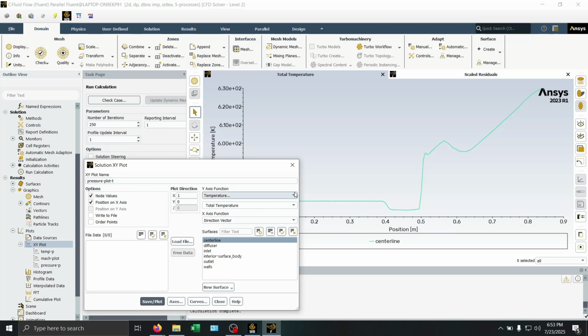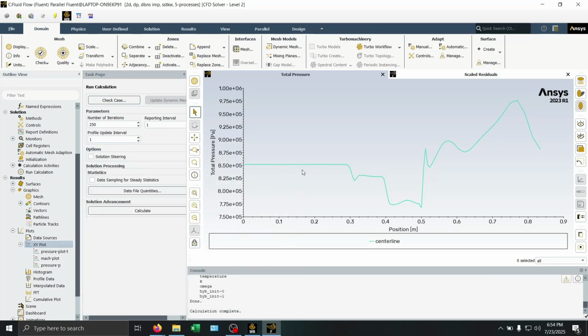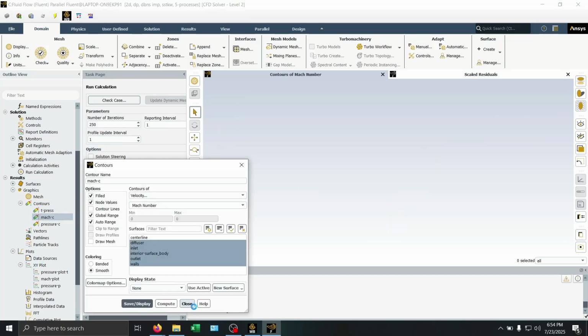And then we have the total pressure. Pressure and total. Same thing across the center line. And this one, right, drops after the shocks, and then it starts to increase throughout the nozzle. So not perfect, but with the losses and friction and other things, it's not quite what we expect from an ideal case.